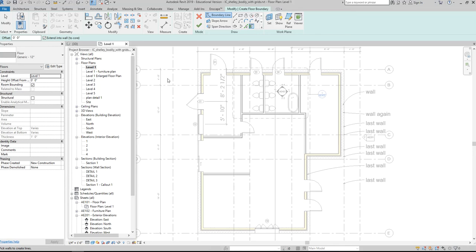This one specifically, you look here and it comes and goes down and it jogs in and moves down a little bit more. Sometimes you'll have holes in the floor for stairs to go through. So the reason we have sketch mode is because you have to draw irregular boundaries for floors, and we need the ability to very easily create those irregular boundaries.